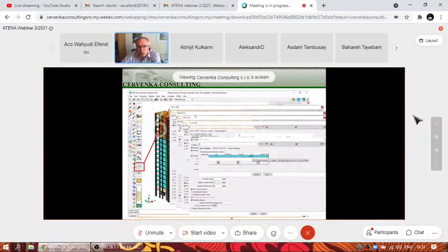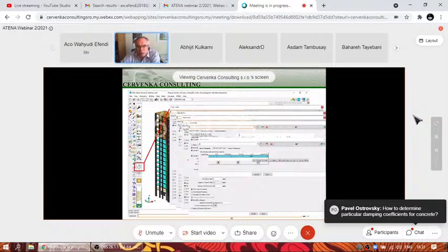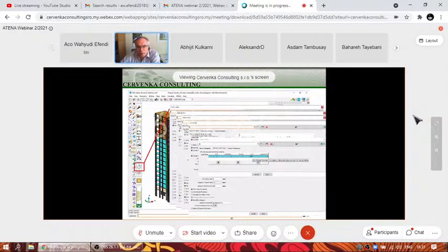So for instance, normally every time you create an interval in GID, you have to repeat the conditions which are fixed, let's say. Yes, for instance, a typical condition is the support. Support that should be in all intervals. So that means you have to define it or copy it from one interval to another.